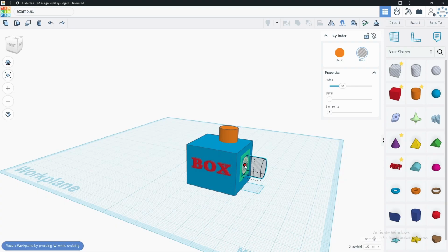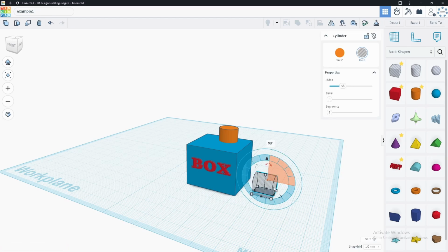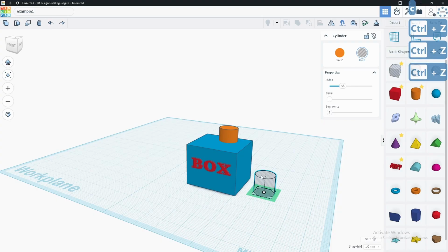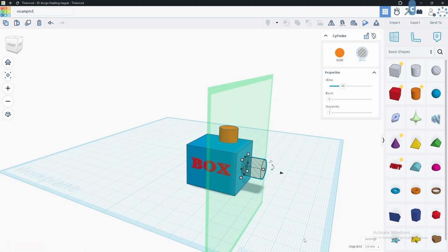So remember, before the cruise tool, I rotated, I slid it over, and then I raised it up. That's a few more steps than doing this. Letter C, click, drag, done. So it saves a lot of time. I like the cruise tool.